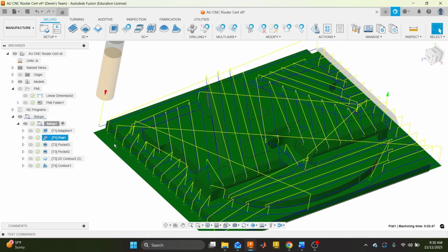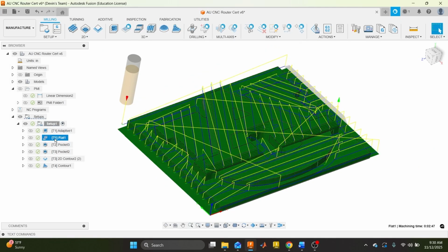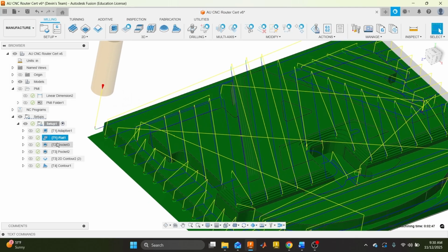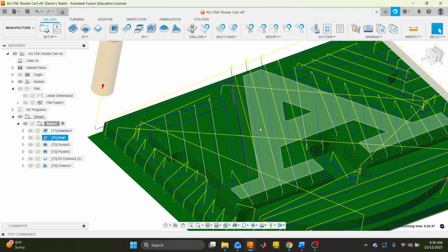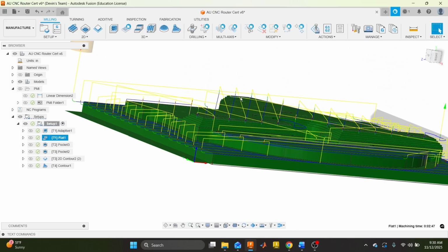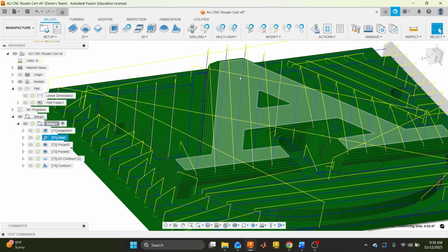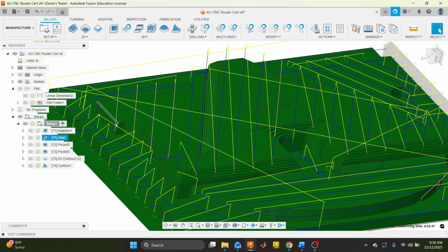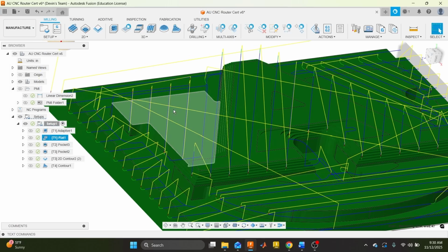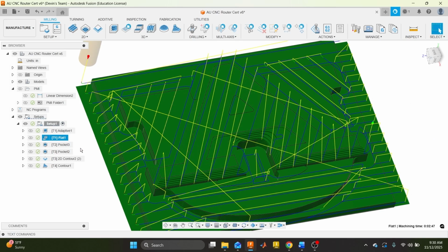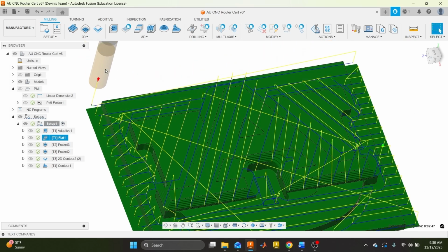Some people like to move it to the end. I just like doing it when this tool is already in the machine, so I can post both of these at once for the Laguna, which is the CNC router that we'll be using for the certification piece. So I hit this flat, and then I machine all of these lines and take the axial dimension, which is the Z component dimension, down to its final measurement. And so there's 0 stock remaining for the Z height. So I do that. Next, we've done everything we can with this 1/2 inch end mill.